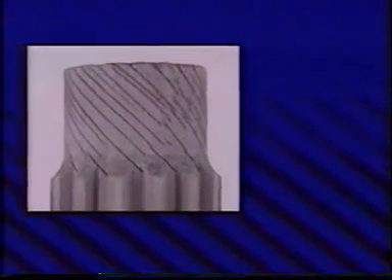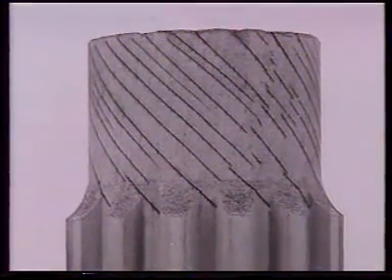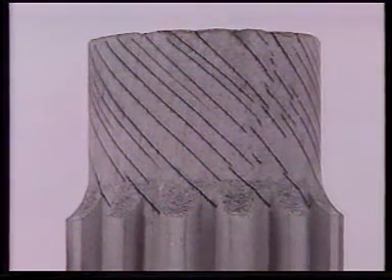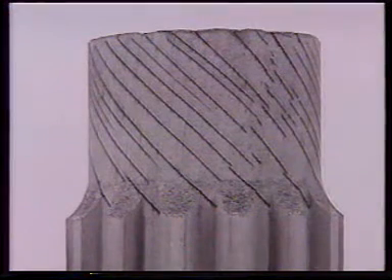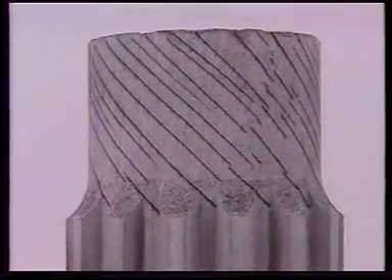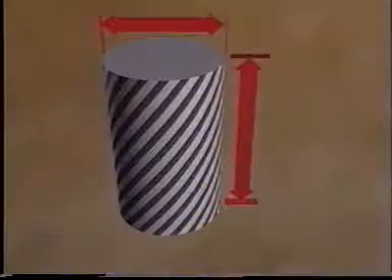The deformation caused by torsion may not be obvious unless there were previous longitudinal reference marks on the shaft prior to twisting. Twisting deformation can be made visible in wrought metals by chemical macro-etching, revealing the originally longitudinal grain flow. Spiral lines in the metal show the deformation. With pure torsional deformation, the length and diameter do not change.